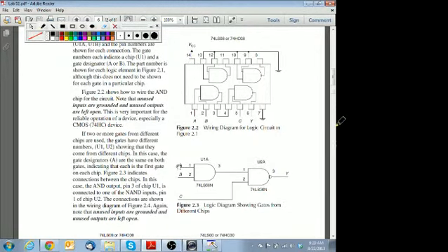Over here at A, B, C, that's just arbitrary decided by the engineer. These are names they pick. They may pick names on these nets, like input, enable, and clock. So this doesn't really tell you any information. What you're looking for is pin numbers. Where do these pin numbers go?